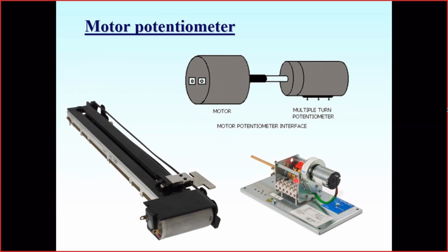Here is a motor that turns a potentiometer and simultaneously, using this belt gear, moves this cartridge back and forth. So if we attach a pen to this cartridge, we get a plotter which draws us a line, and if we pull the paper, we get a recorder. So this potentiometer assembled together with a motor, or better to say motors assembled together with a potentiometer, is the center